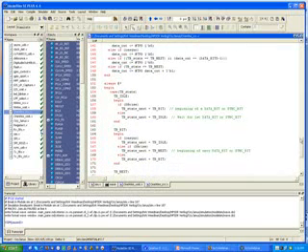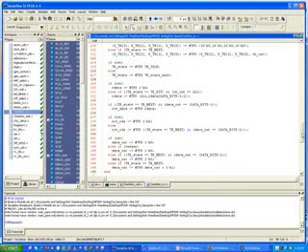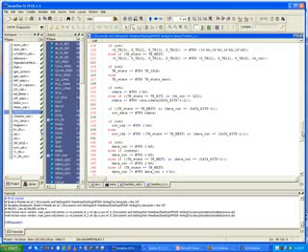So how does my state machine work? Well, you'll notice that this part of the code, this second always block, is combinational logic. Everything is based upon the state, this TB underscore state. Okay? And TB state is the output of a set of flip-flops.